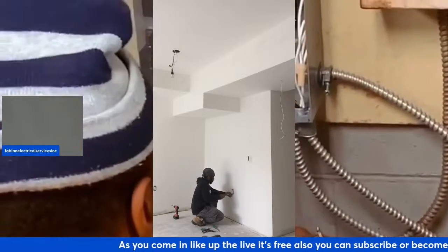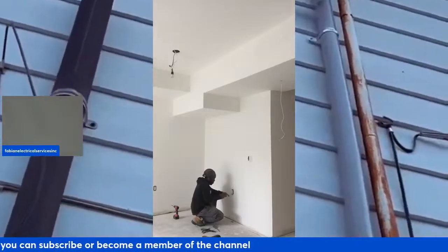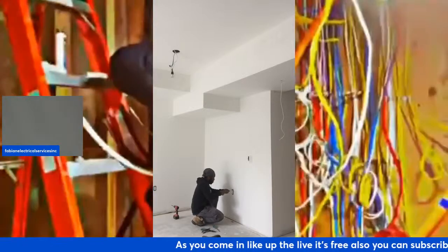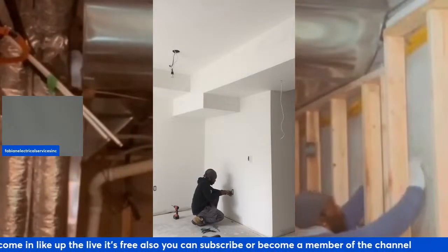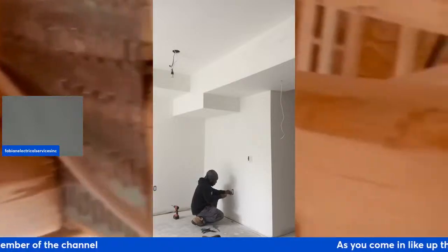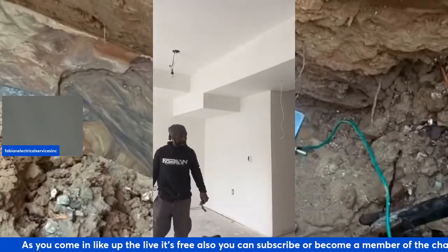They are required in areas with water such as kitchens, bathrooms, and outdoors. A GFCI monitors the current flowing to a device and the current returning from it. Under normal conditions, the amount of current going out should be equal to the amount coming back in. If the GFCI detects a difference of about 5 milliamps, it means some current is being diverted, a ground fault. The GFCI immediately cuts the power to prevent a shock, protecting you from potential electrocution, burns, or other injuries.